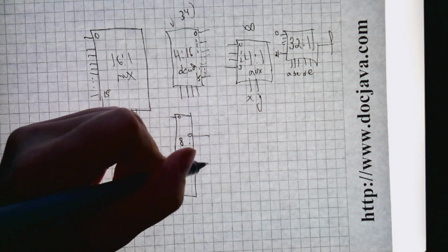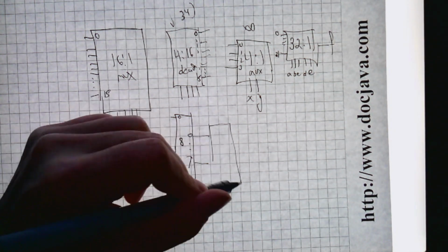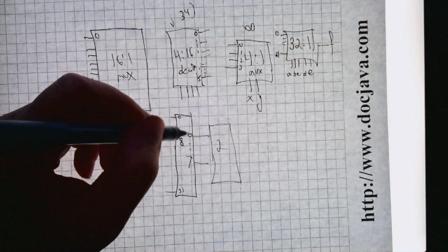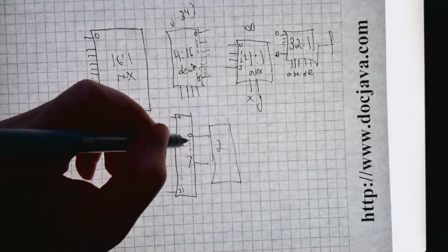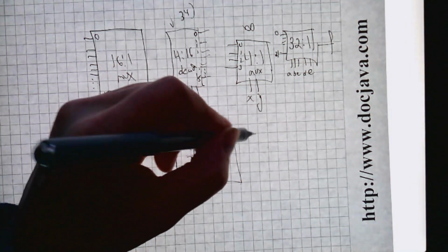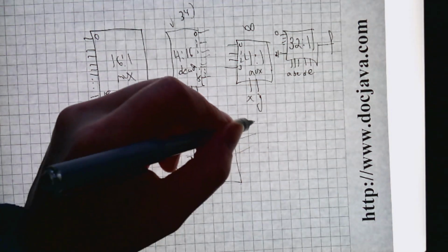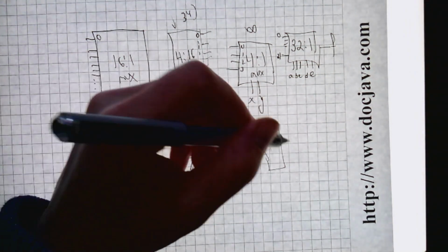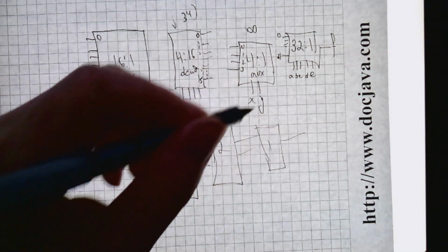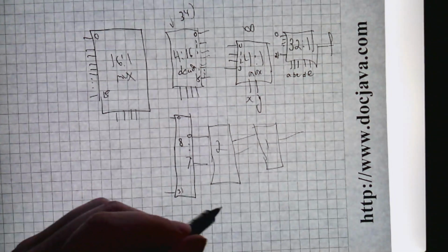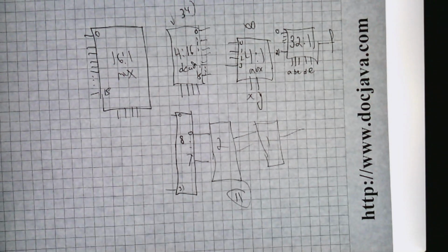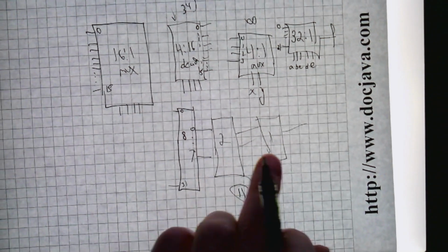So the next stage, you've got to have at least 2, it's the only way to handle the 8 inputs. And the next stage, you're going to need 1. You only use half the multiplexer. And so, looks like I need 11. Right? 8 plus 2 plus 1.